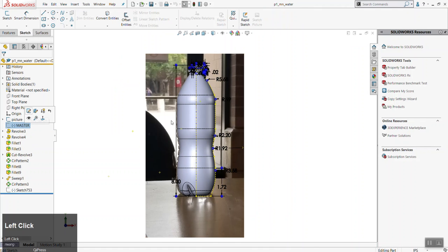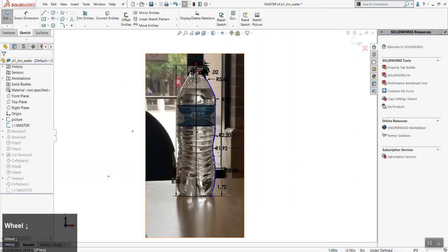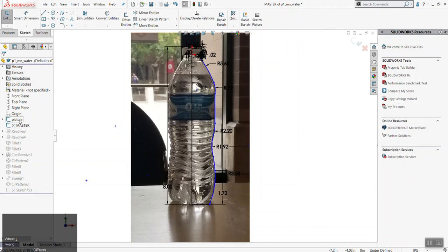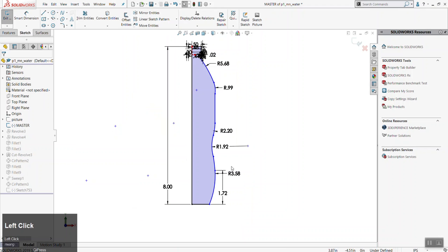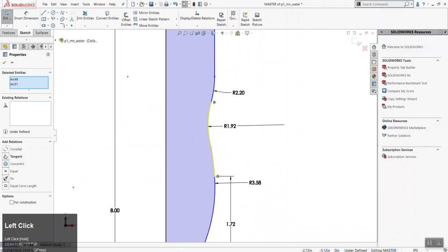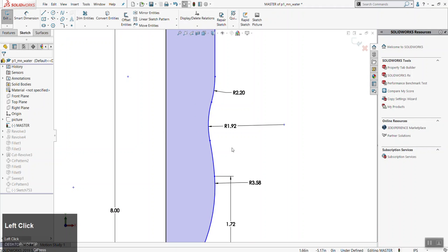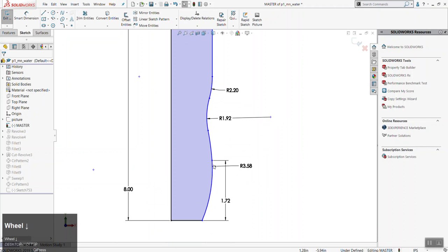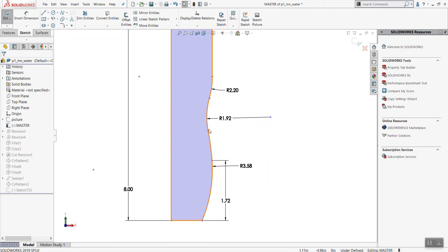So if we look at this, yeah, same thing as what I just showed. You could define these the same way. It doesn't look like this is tangent to me, so just trying to catch things like that helps. Here it looks like you have two arcs when one might do. Again, I applaud the accuracy, but whenever you can simplify, that's not necessarily a bad thing.